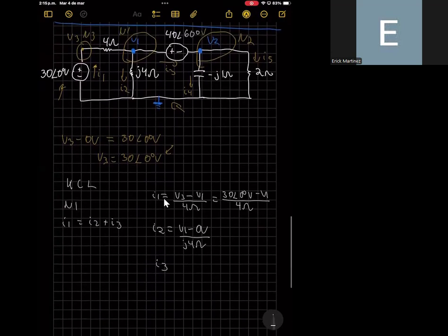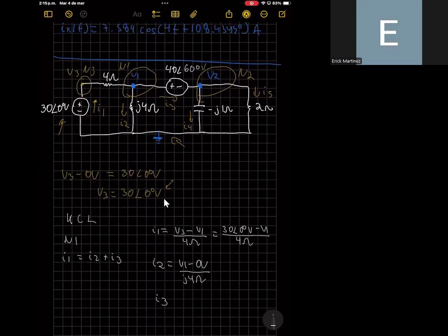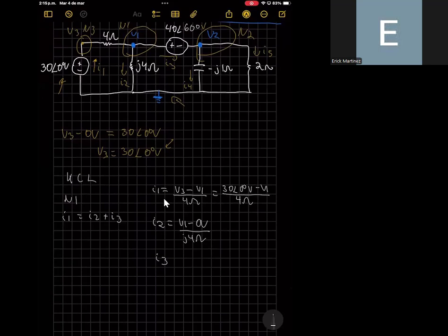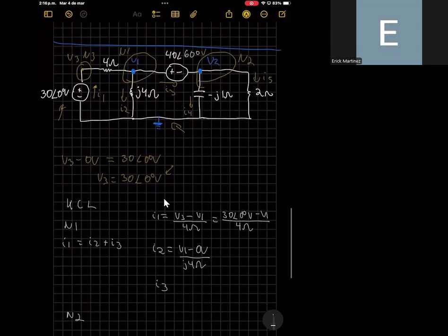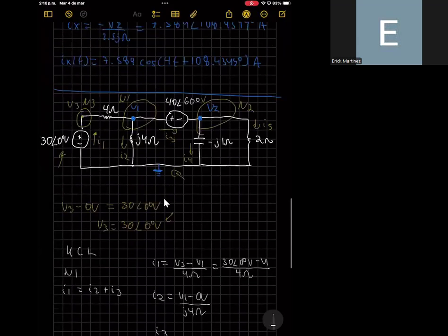But here we can face a problem. Because we need to define this Kirchhoff current law, but we know the voltage of this element, but we do not have a direct way to compute the resistance or know what is the resistance through this branch in which I3 is flowing. So we need to deal with that in the case of this circuit. So for now, let's compute again the Kirchhoff current law, but for node number 2. So here you can see that we have I3 that is entering this node.